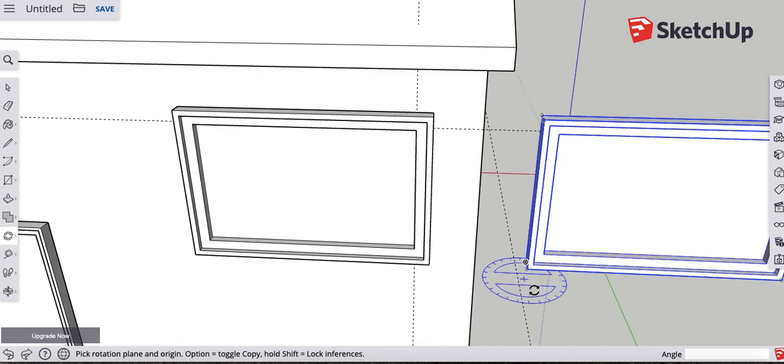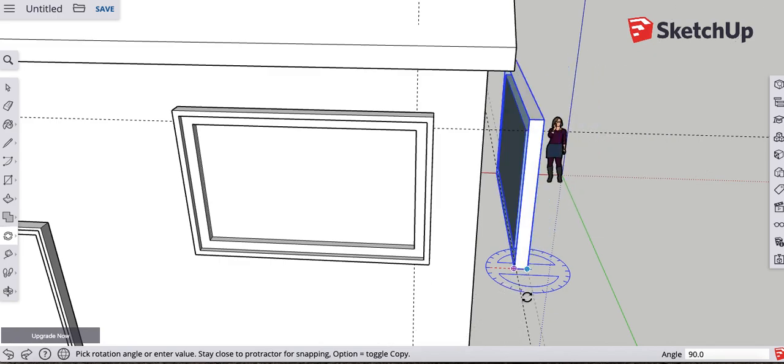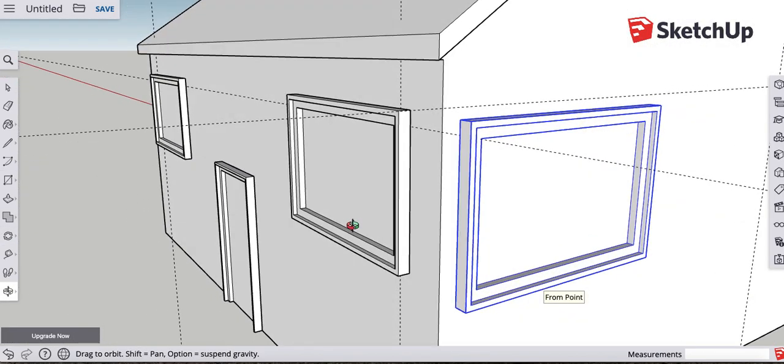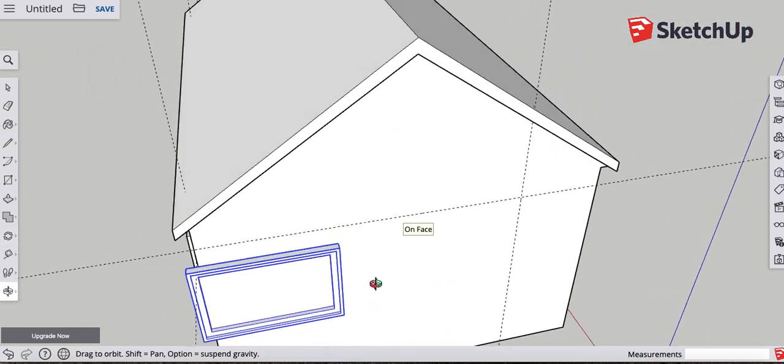So again, let's go back. Get your rotate tool, click on a corner, but you need the blue compass so that it's along the ground. Click once. Drag it out horizontally, click twice. And now just move your mouse in the direction that you want to rotate it, and it should snap to what's called your green axis there. Okay, now I can easily just move this into position.